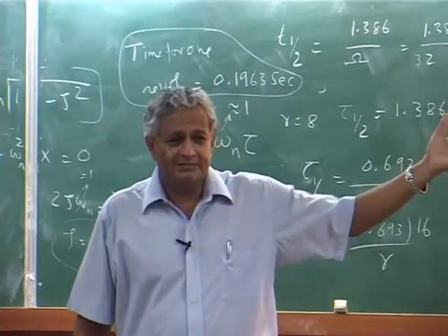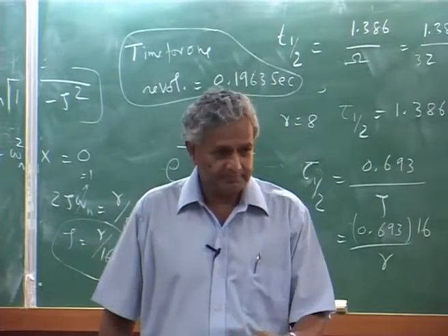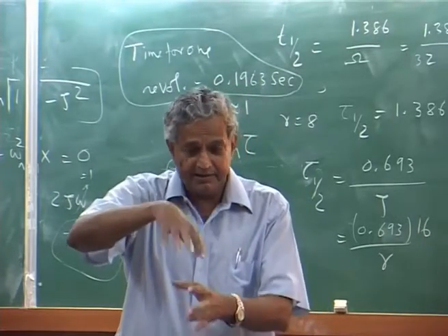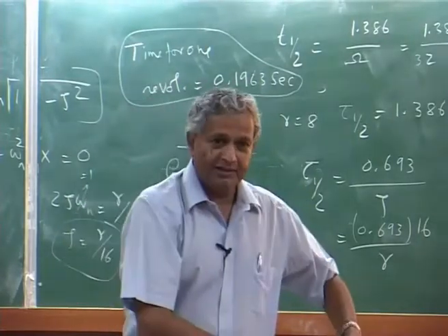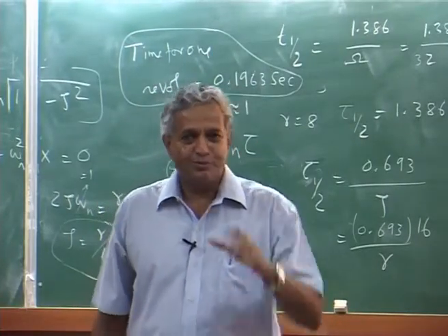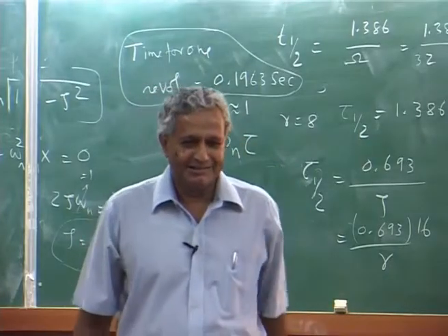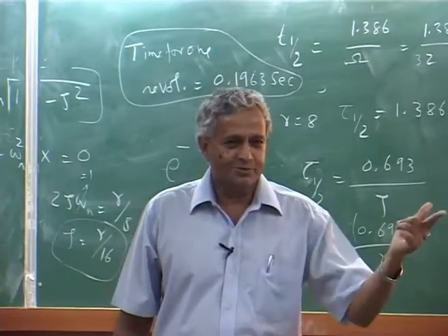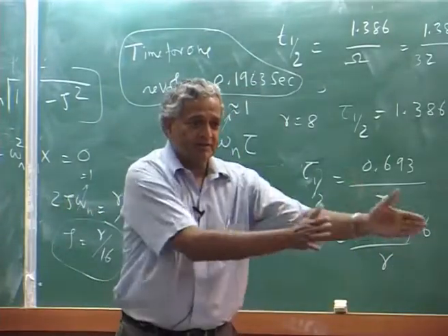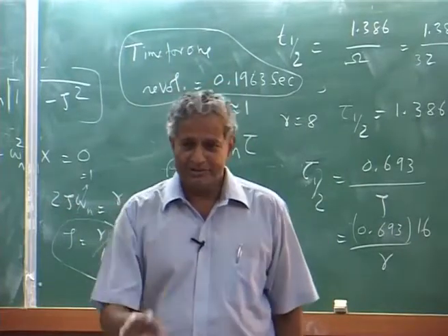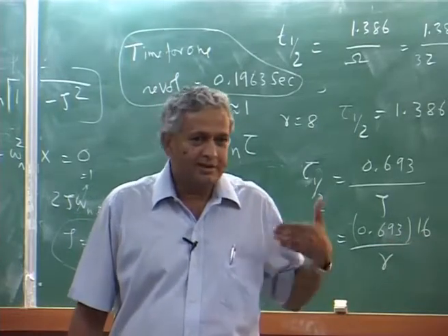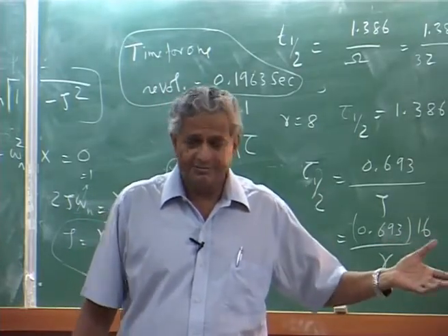The pilot gives an input to the rotor blade, the blade immediately flaps, then it gives the hub moments and the helicopter responds. The delay between pilot input and the response of the blade, I am neglecting. I say that it responds instantaneously. That means I neglect the flap dynamics and look at the steady state value.